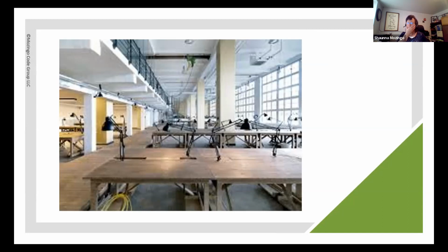Let's see, what else changed in there? It's still the lights have to turn off within 20 minutes of the occupants leaving, but it did add a new exception for general lighting to be turned off by a time switch. It added an exception: you don't have to turn off within 20 minutes if you do the time switch. So that's very common.